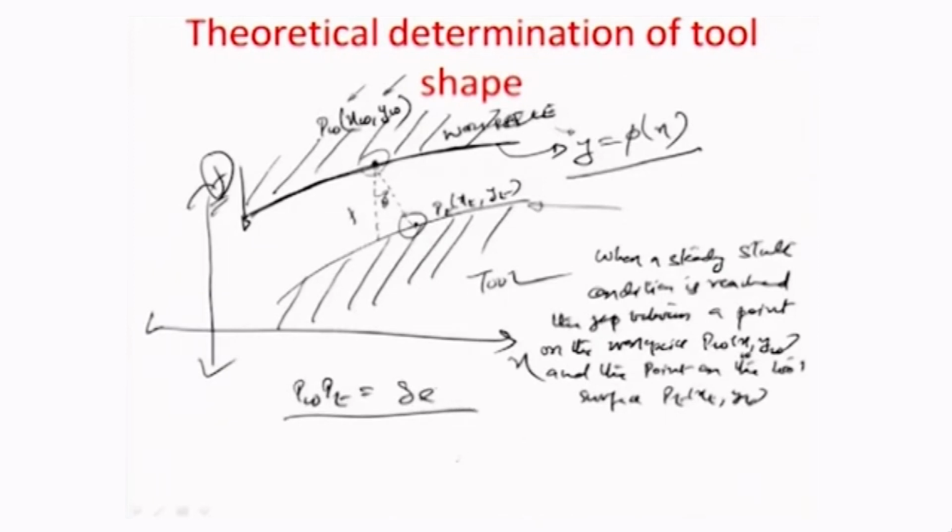We know what G is. It is a function of many things, as you know: the atomic weight, the available voltage, the conductivity, the density of the workpiece material, maybe iron or copper, whatever is being removed or machined, and so on and so forth.